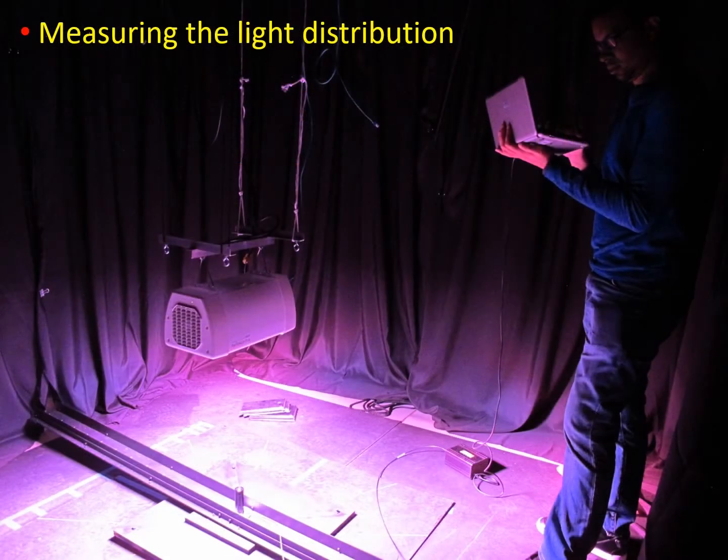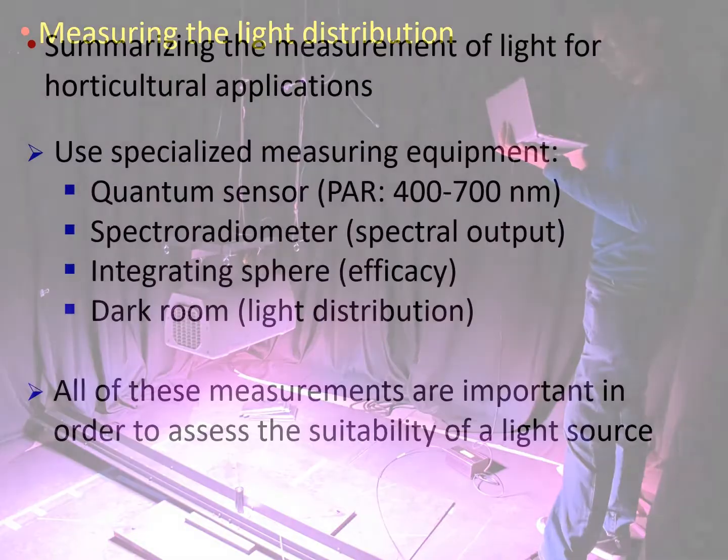If we want to assess how a particular light fixture distributes the light across a growing area, we can use a darkroom as shown in this slide. A light sensor is moved across a predetermined measurement grid placed some distance below the lamp, and the measurements are used to make light distribution maps. These measurements can also be used to calculate the light uniformity across the growing area when an array of lamps or fixtures is mounted overhead.